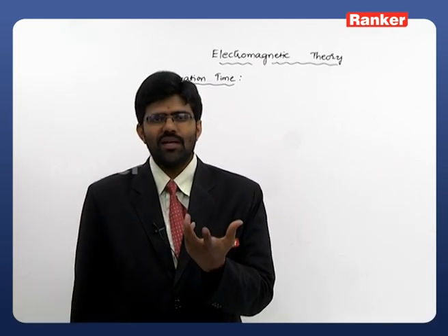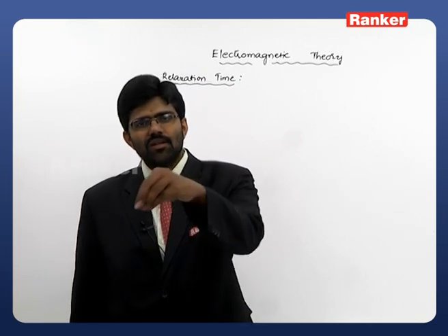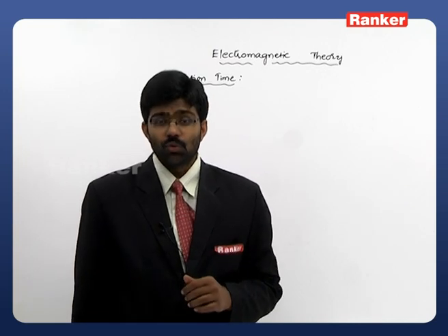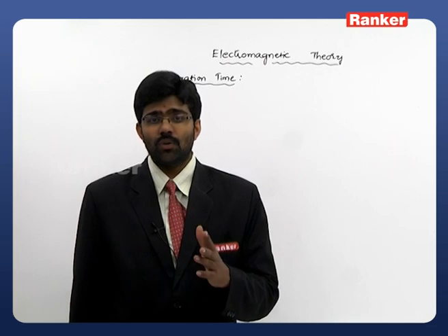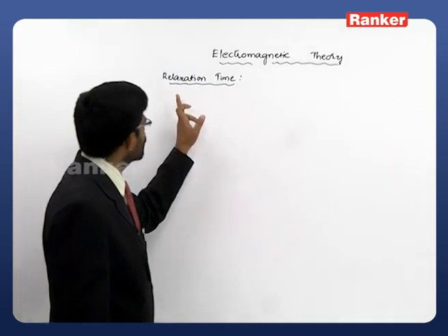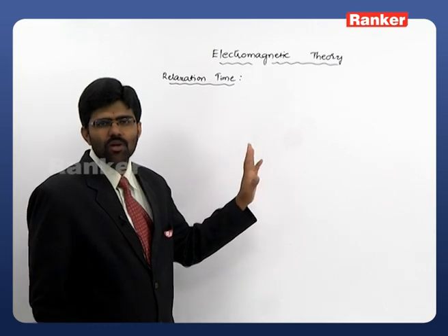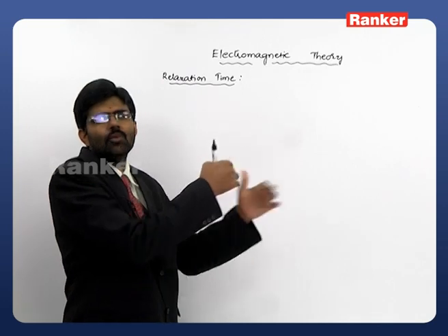Because to store some electric energy, what we require is charge. So whenever we place that particular charge in a volume, it must remain as charge for a long duration. We will examine how much time a particular charge will remain as charge with the help of relaxation time. Later I will define what this relaxation time is also. For that, I will take all the equations we have till now and try to rearrange them.